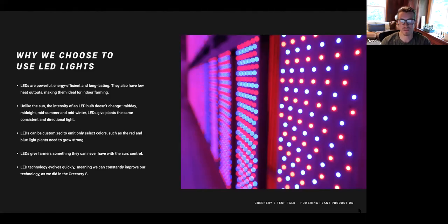And lastly, LEDs, or light emitting diodes. As I said, they produce the longest lasting, most energy efficient lighting available today. An LED utilizes a semiconductor that's rich in electrons and a semiconductor rich in holes. Passing a current through the junction of these 2 materials combines the electrons with those holes and produces photons. Photons are just the unit of light that you can see.